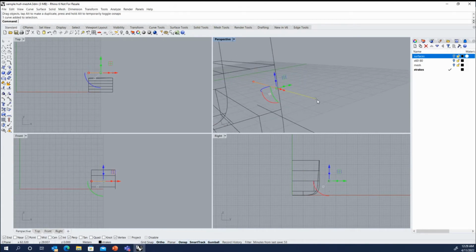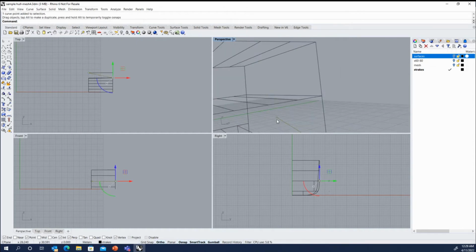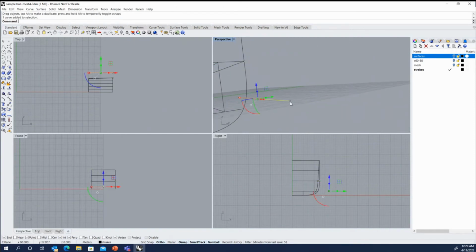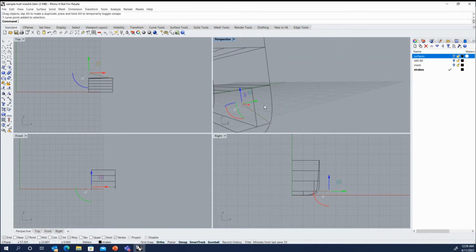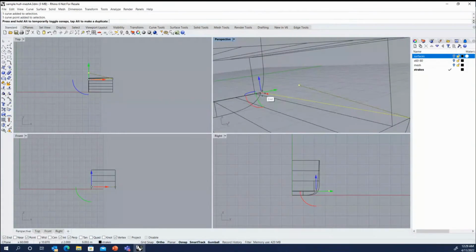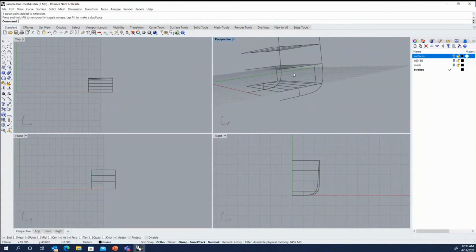And it'll tell you which one is currently active, what it's snapping to, whether it's snapping to a perpendicular connection, an endpoint, or an intersection. And I know I want to snap to the endpoints, but I can just be careful to make sure it's hovering to the right one. So if I came up here, there's my apparent intersection, perpendicular, but I want the end of the deck there. So if there's too many things in the area, it'll bring up a list like that, so you can refine which item you're selecting.